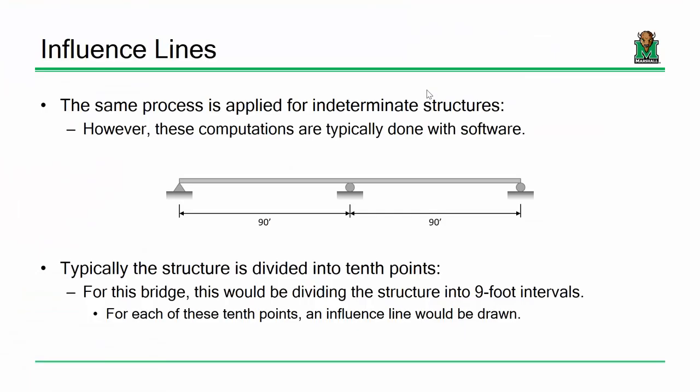All right. Okay, so what I mean by that, where'd my pen go? There we go. So keep in mind that throughout everything I'm about to draw, my point of interest is right here. Now what that influence line was telling me is that if I place that truck somewhere right here, I'm going to get positive bending. Now why am I going to get positive bending? Well, my beam's probably going to deflect something like this. Make sense? It's going to deflect downward.